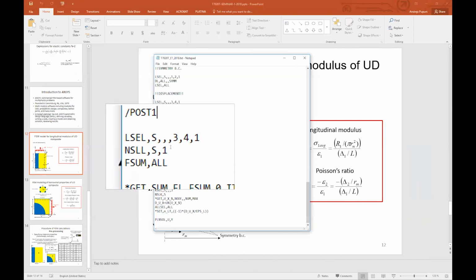Hence here you can see the importance of actually following the numbering of your geometrical entities in the model. If you know the numbers of the lines, you're in total control of reviewing results and extracting certain parameters, and without a doubt you can select exactly what you want, and you can select it fairly easily. So I highly recommend that whenever you create a geometry, you always know which line has which number, so that later on you can refer to this line and do the operations.